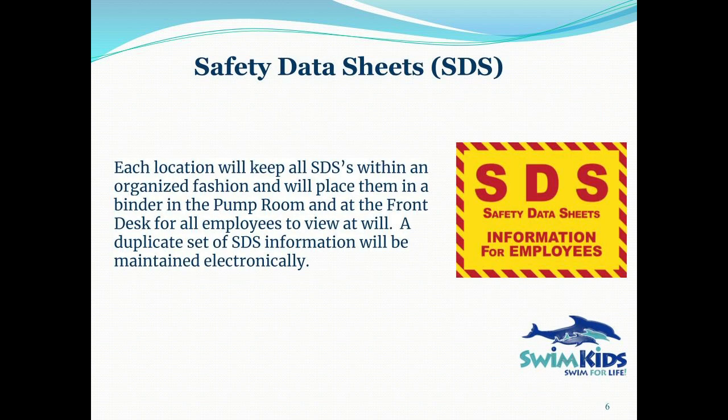Safety data sheets, or SDS for short, are forms that identify a particular chemical and its supplier. It will provide you with information regarding physical hazards like fire or reactivity to other chemicals, as well as health hazards such as skin contact or inhalation. The SDS also provides information regarding prevention, steps you can take to work safely to reduce or prevent exposure, or in an emergency, appropriate responses for various situations such as first aid, fire, or accidental release.